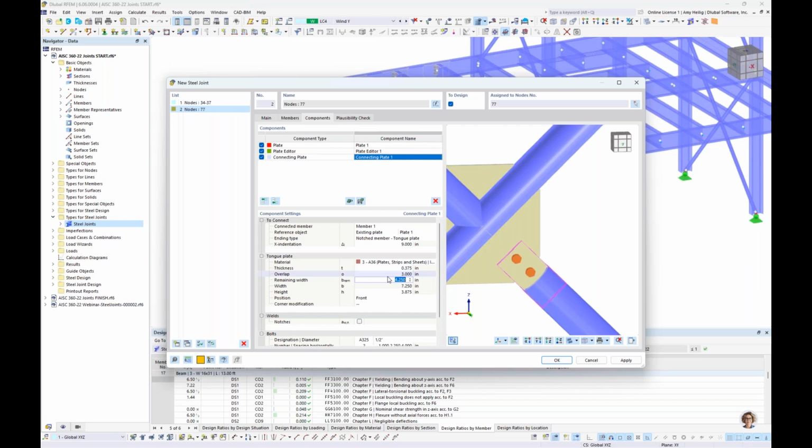The remaining width is going to be set to 6 inches, and because I set my total X indentation to 9 inches here, and then we also see the overlap in the remaining width set at 3 and 6, the program's intelligent enough to set automatically the width to 9 inches. So then the height is going to be adjusted to 4.75 inches.